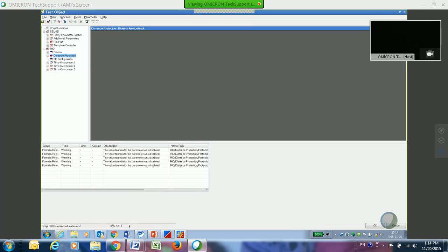Okay, larger of the two. Yes. Now, if you want, you can turn one or the other off, and then you can have it specifically do whatever you want, whether it's absolute or relative. But a lot of times people will put both of those in there, and it just takes the larger of the two. If both are selected, the larger will come into action. Yes. Okay, thank you.